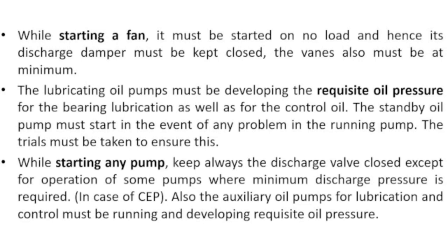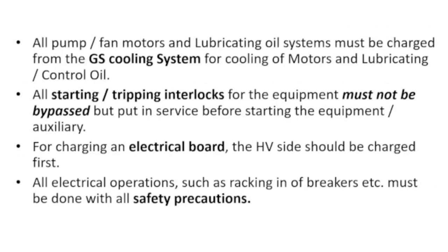While starting any pump, keep always the discharge valve closed except for the operation of some pumps where minimum discharge pressure is required, as in case of CEP. Also the auxiliary oil pumps for lubrication and control must be running and developing requisite oil pressure. All pump or fan motors and lubricating oil systems must be charged from the GS cooling system for cooling of motors and lubricating or control oil.